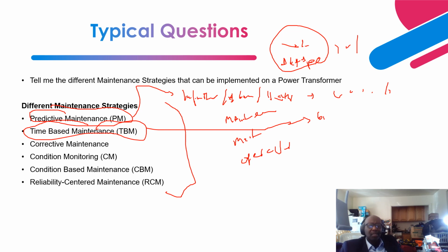This is based on a 6-year cycle, right? Basically, where the transformer is de-energized and taken out of service, and you go with your maintenance crew and perform inspections, right, and perform testing, right, and routine testing is performed on the transformer. So the routine testing that are listed on the previous slides are typical testing that is performed, right? Okay, so this becomes part of your maintenance history test results.